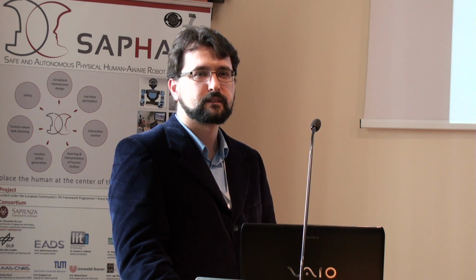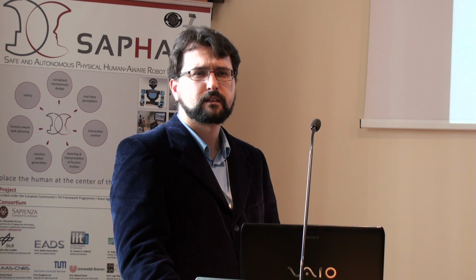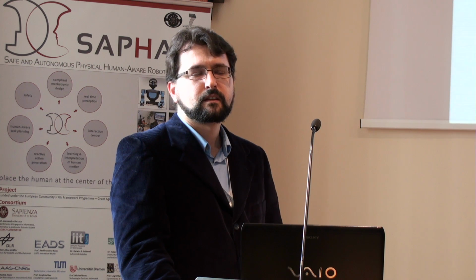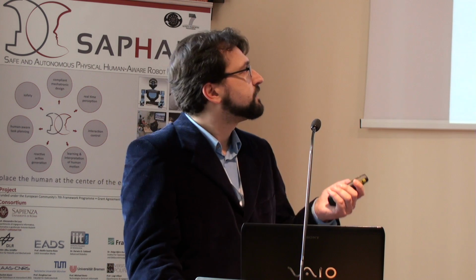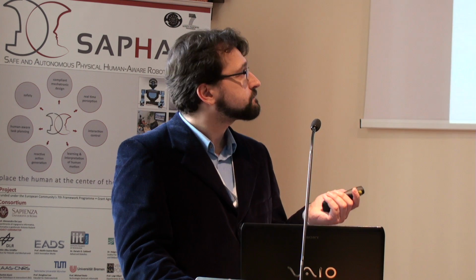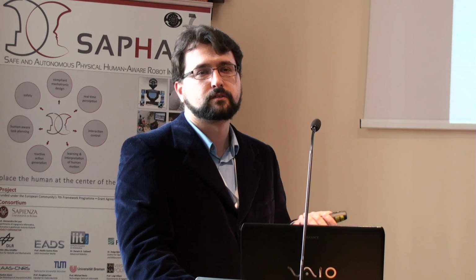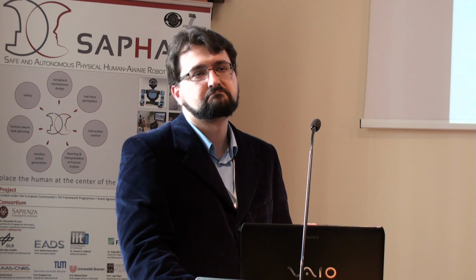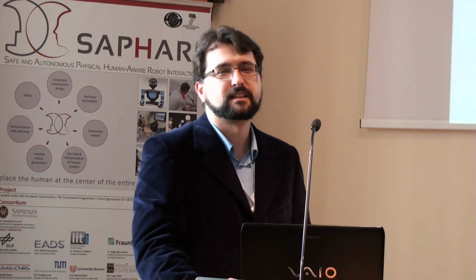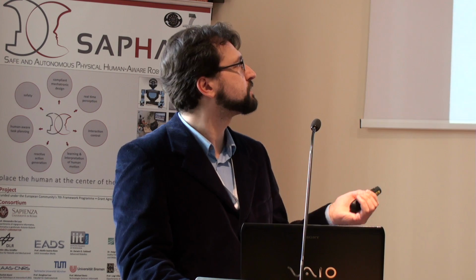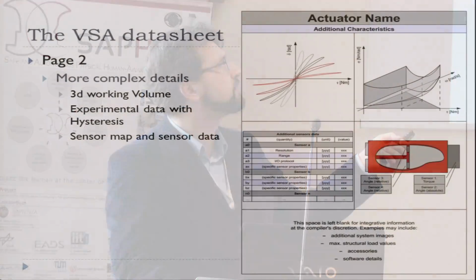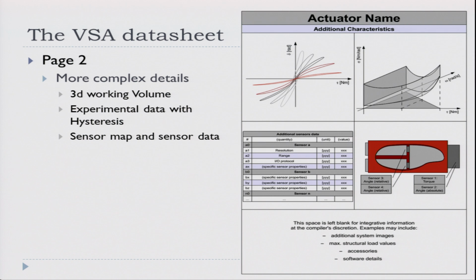Yes? How do you synchronize the two motors, for example, in this case? In our actuator, we have two independent PID controllers with high gains, and it works. But it depends on the precision you want. Part of the hysteresis, for example, is also due to the imperfect control of the motors. Depending on how much precision you want, you could need better controllers.